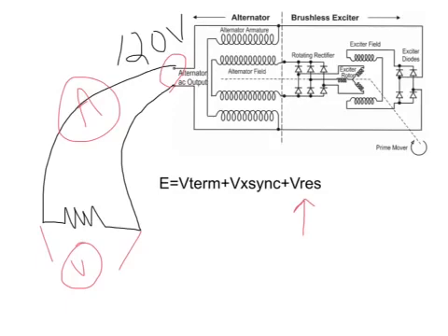That stands for synchronous reactance. Synchronous reactance is the combination of voltage due to armature reaction, which is that distortion of the magnetic field, and voltage due to inductive reactance. Remember, this alternator armature is a coil. Anytime we have a coil, it has the property of inductance, and inductance is the property of an electric circuit that opposes a change in current.